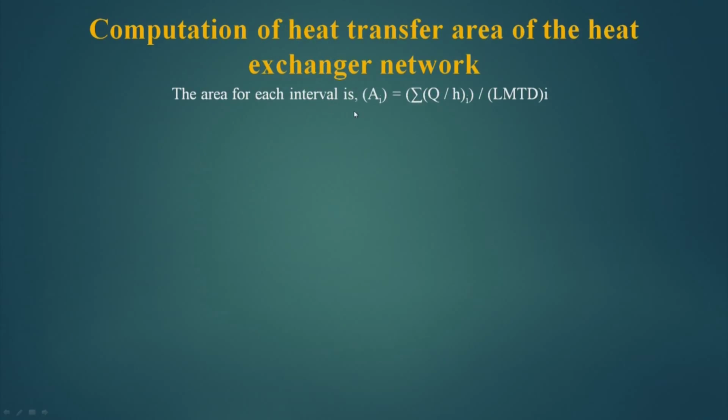Now, the area of a temperature interval is given by the summation Q by H value for that interval divided by the LMTD of that interval.